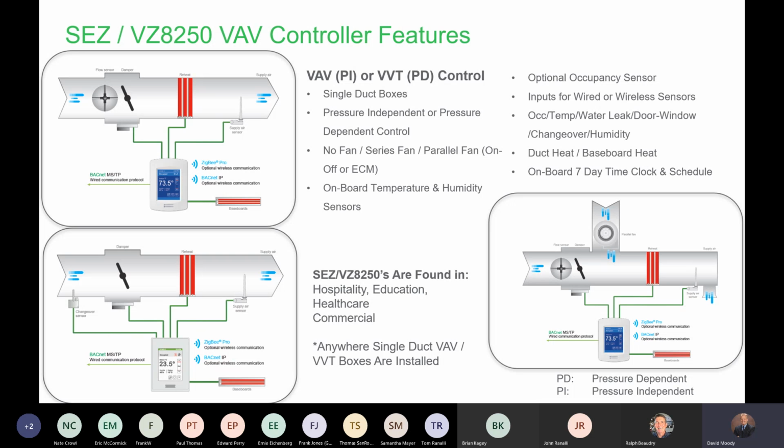And as you can see, as I've been talking here on the slide deck, it handles every VAV application except dual duct. If you have a dual duct, it won't work with a dual duct. It's just not designed for that. And if you have an application for dual duct, it's something that we could talk about and see how we could address that. But out of the box, it is not something that it does all on its own.